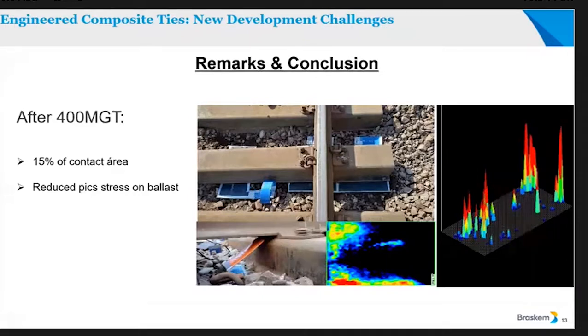The peaks on the ballast were reduced exactly because the interaction between the ballast and tie was much better when you compare with concrete ties or steel ties.